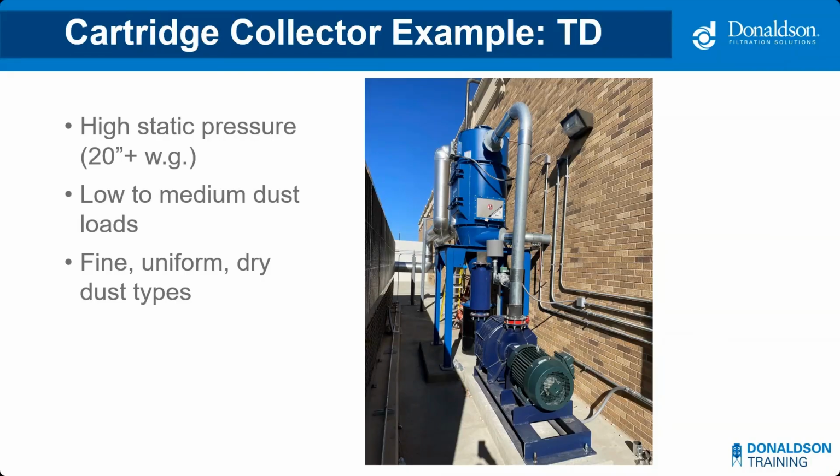We've got a pressure blower on there. It has a tangential inlet so that when the dust comes in, you get that cyclone effect for the heavier stuff to drop out. You can see it's got an explosion vent on the outside as well.